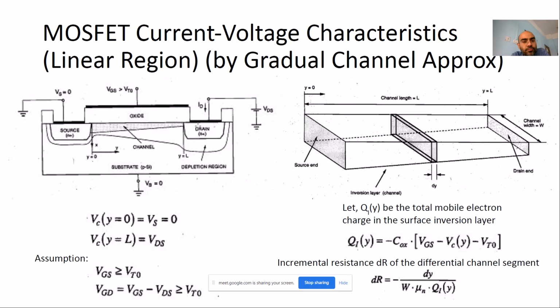Particularly, the source is grounded and we are applying the positive voltage at the drain side. So drain is N plus. When we apply the positive voltage, then the depletion region is increasing significantly. So that's why the charge density is more on the source side rather than on the drain side, because the depletion region is more on the drain side. So it is eating up the channel particularly. Very nice, so you got it right.